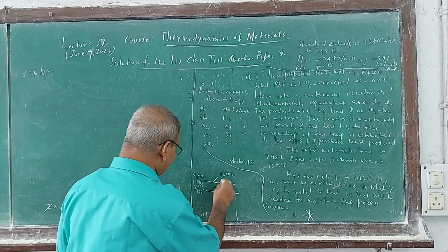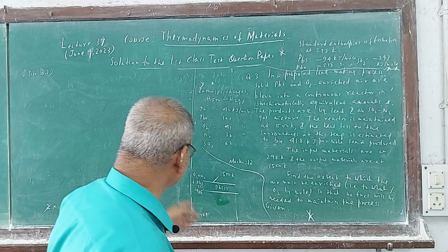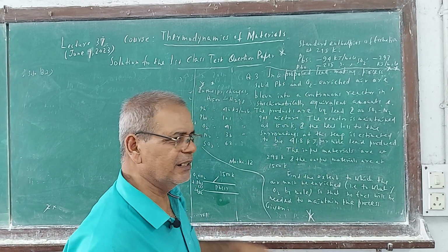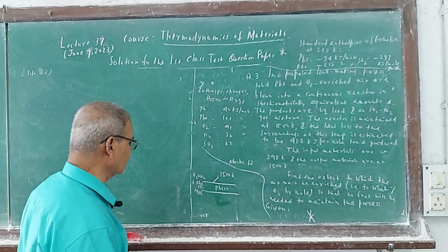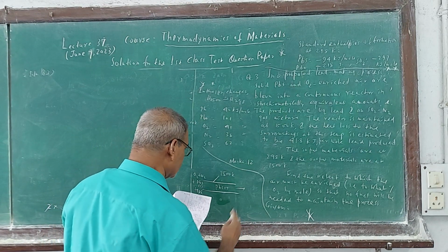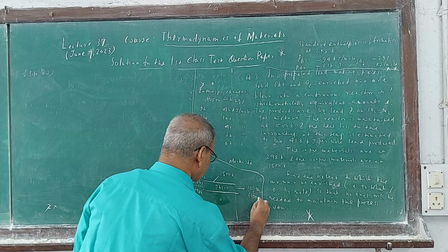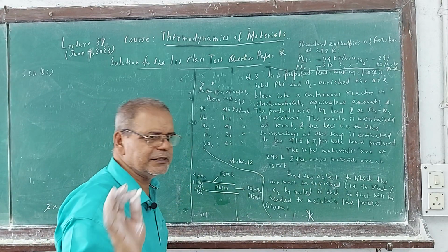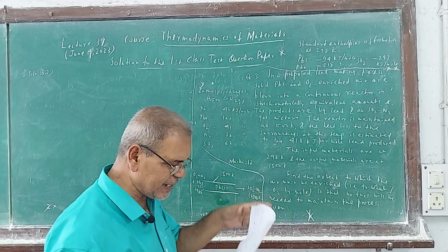This is the furnace. This is an exothermic reaction, and that is why the temperature is 1500, because of the exothermic reaction. Here also PbS is treated as a fuel, so no extra fuel is required. No other exothermic source is required. What is coming out? You tell me the figure: SO2, N2, given to you at 1500 Kelvin. They are exiting at this temperature, and liquid lead also at 1500 Kelvin. So these are the products. The lead stays back in the furnace and the gas leaves.